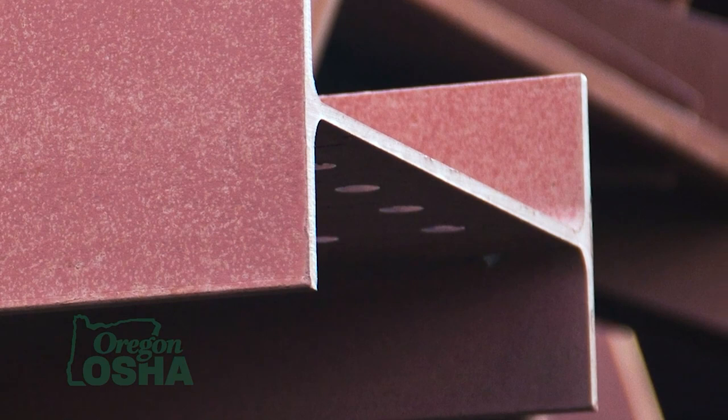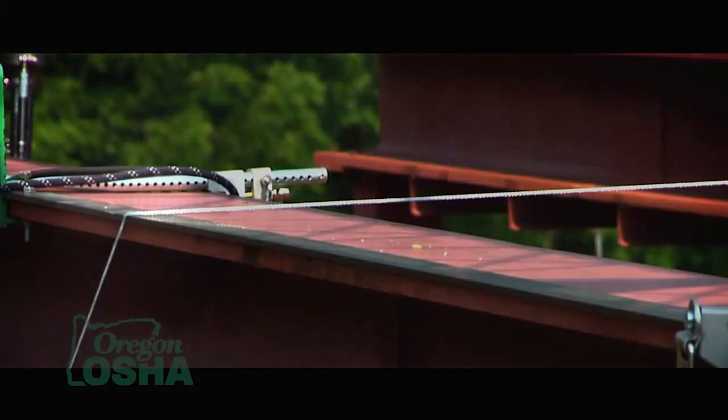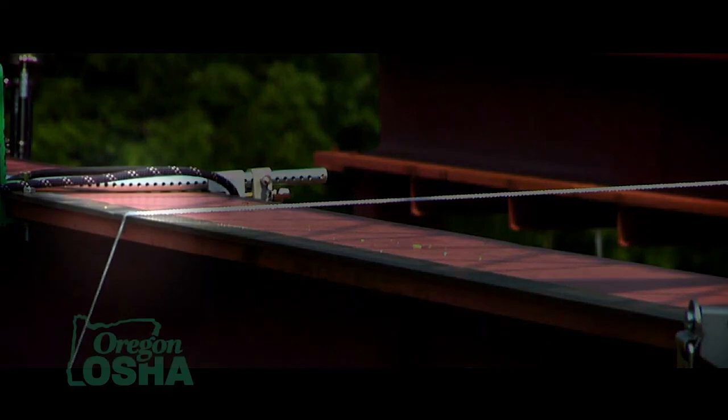And there are some definite hazards there when people are working on leading edges that are sharp and don't have the proper equipment or don't have their systems properly put in place. We have the hazard of cutting the lifeline, definitely whether it's web or cable. We do have cut hazards that are there. There's also, as we said earlier, the clearance hazards that go along with that as well.